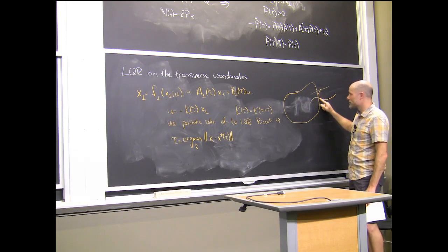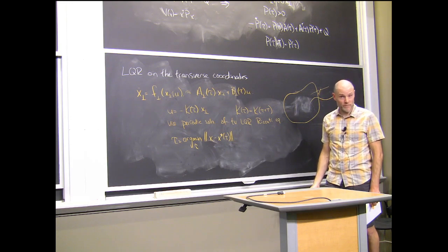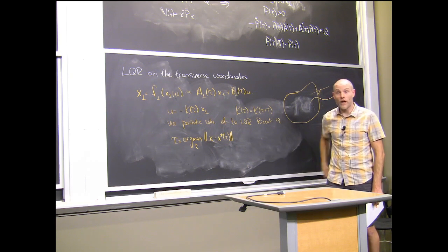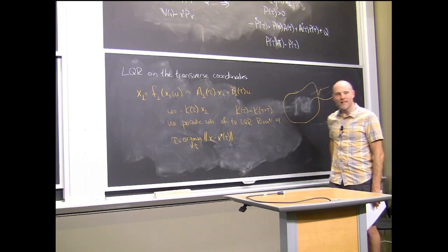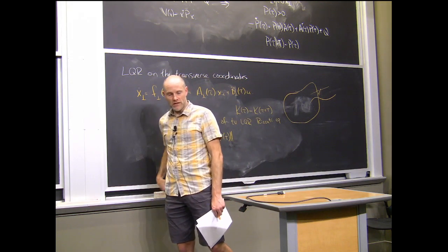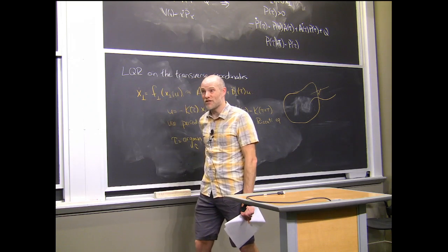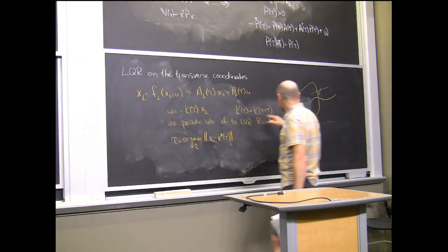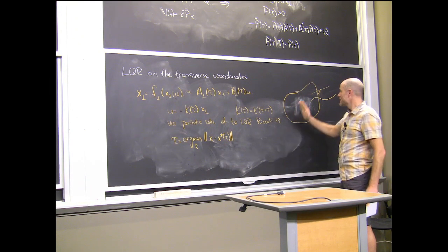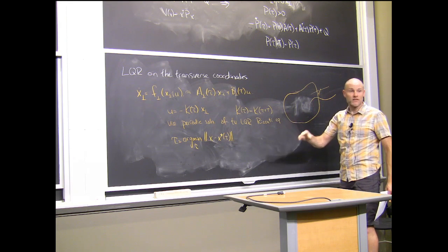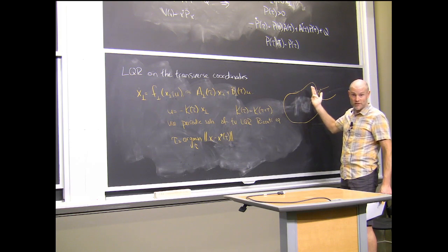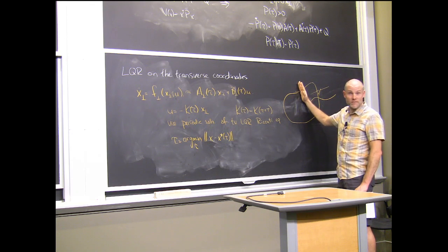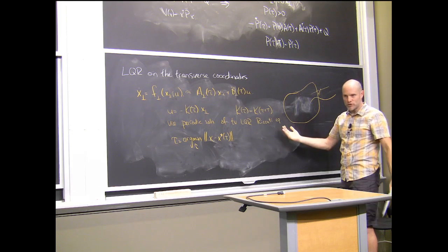There's actually a subtle point here too. If I have, let's say, a compass gait walking robot, and I put a torque at the hip, now I have two leg angles, one actuator, underactuated. If you try to stabilize the thing completely in time, and you look at the controllability gradients, you realize the hip doesn't have much authority to control the bottom toe. It's just weakly controllable in that sense. Designing an LQR controller in the full state, you might be able to find one, but it's going to have really big gains because it's very hard for that system to move along the trajectory. There's an actuator that could push itself along the trajectory, but that's very hard for the hip actuator in the compass gait. So in practice, going from the full coordinate system to the reduced coordinate system, you get back to beautiful small gains and good performance.